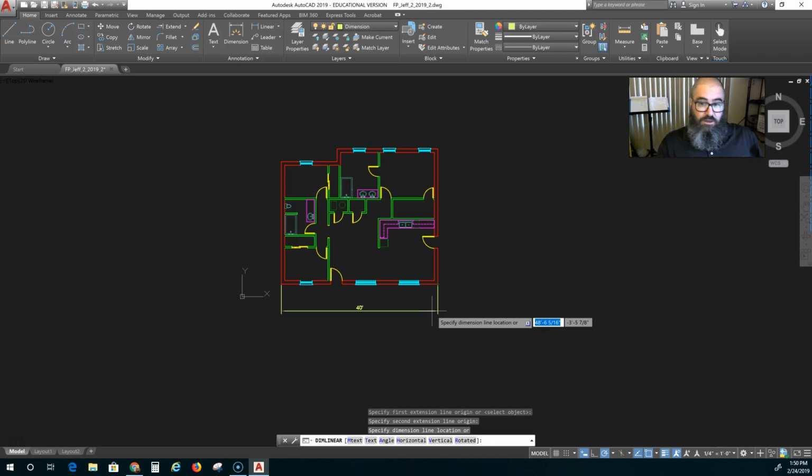So I want this to be 8 feet from the house. So I am going to type the at symbol. I'll hit the shift button, and it's actually at the 2. Okay, now it says at, and I'm going to put in an XY dimension. So first is my X, and I want that to be 0 because I don't want to go anywhere left or right.